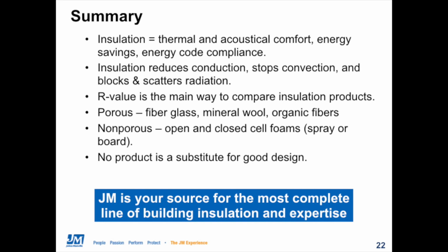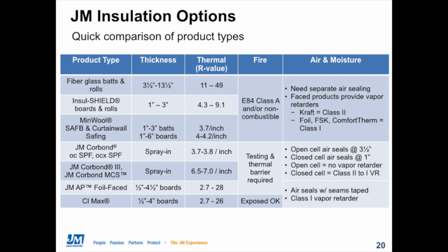Okay. Does mineral wool have an R value? Mineral wool does have an R value, even though we often use it for sound and fire control. Actually, we can jump back up to that because we have that on the slide. Mineral wool R value tends to range between R 3.7 to R 4.2 per inch. So very comparable, sometimes even a little bit higher than what we get out of fiberglass.